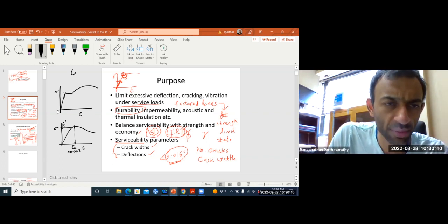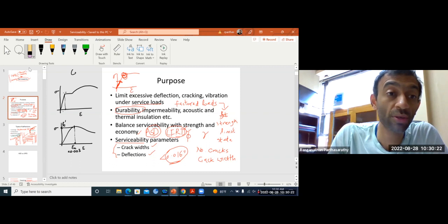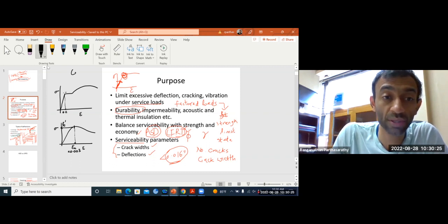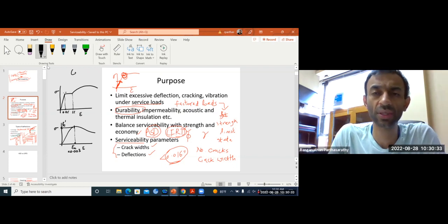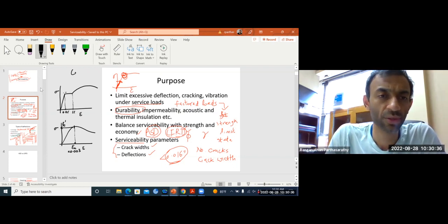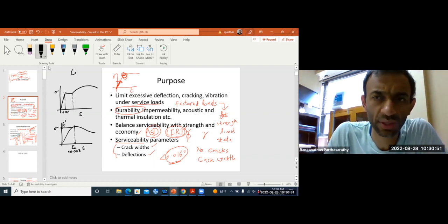Now here this yield point is at 0.2%. Just a second. 0.002, yeah, so 0.2%. It starts to yield, and the hardening starts at 1%. Okay, approximate value. Let me check the approximate value. Yes, that's right. It is at 1%.